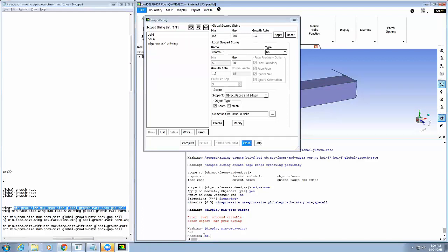Is that with respect to a body of influence, or that's just your general meshing min proc size? That one was minimum proximity sizing. Okay. I just put a general one, I don't have proximity sizing. I didn't have one for the front wing, rear wing, because I generally knew the minimum. My minimum size was like 2 mils, so I know if I want 3 mils, my minimum has to be this. And then if there are other places, I really wouldn't care.